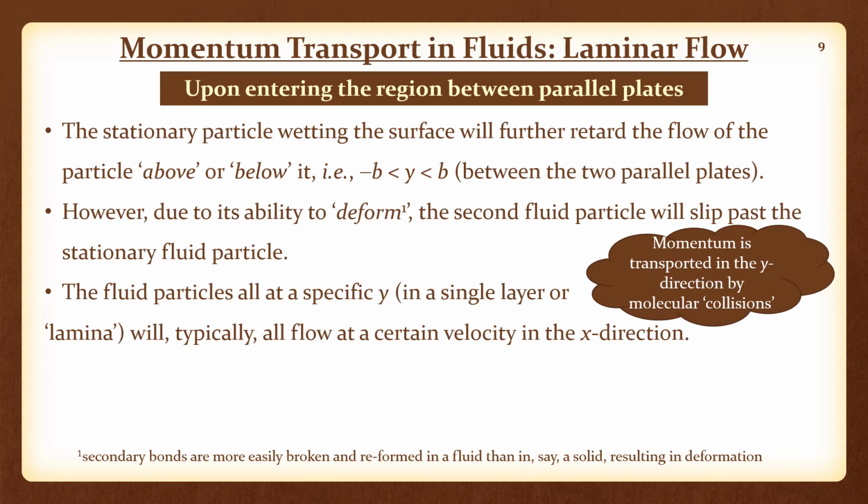So unless such very large quantities of momentum get transported in the y direction to the solid surfaces, the solid surface will absorb all the momentum that it picks up, and it will remain stationary. Therefore, the x momentum that is picked up, that is removed by way of friction, is transported in the y direction to the solid surface. The solid surface remains stationary, and subsequent to it, each and every layer of fluid has slightly more and more momentum available to it.